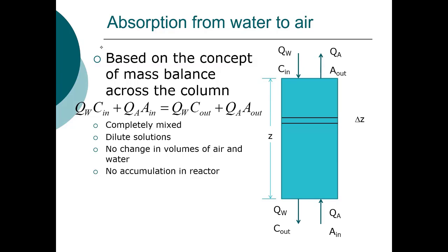The difference is that if we have efficient mass transfer, then we can assume that the mass in the water leaving is much less than the mass in the air leaving. So remember, now we're looking at removing it from the water to the air. So if we have efficient mass transfer, then the mass in the water leaving is much less than the mass in the air leaving.